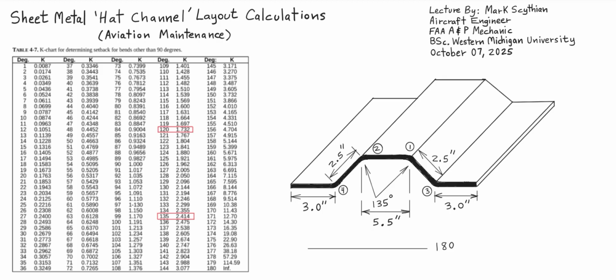Next, we have to identify that the bend is actually not 135 degrees, but if it was a straight line, that would imply 180 degrees, so the final bend is 135 degrees subtracted from 180, so the actual implemented bend is 45 degrees. So the complementary and supplementary angles, unless otherwise specified, are also consistently 45 degrees throughout the entire structure.